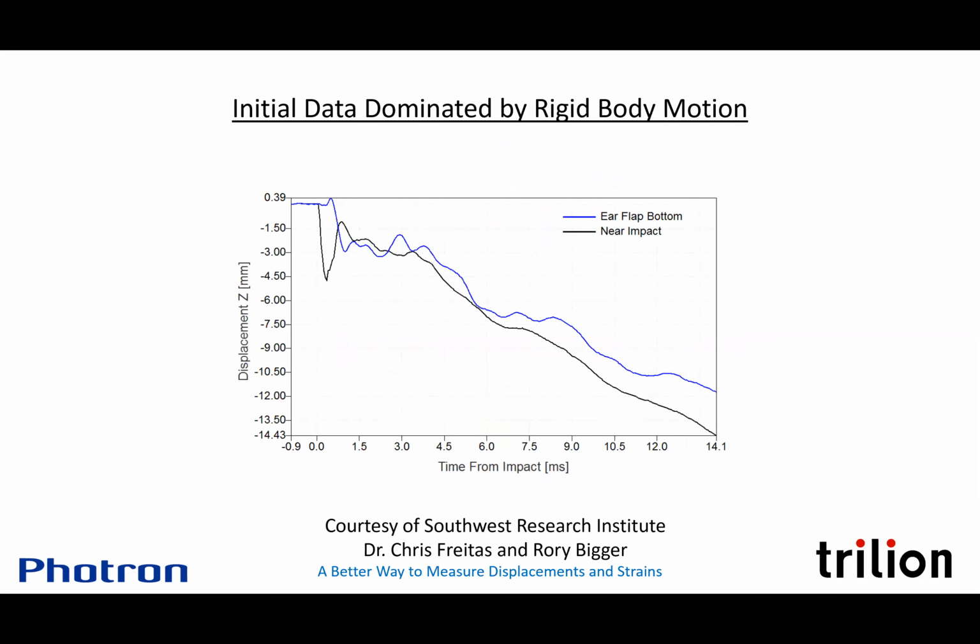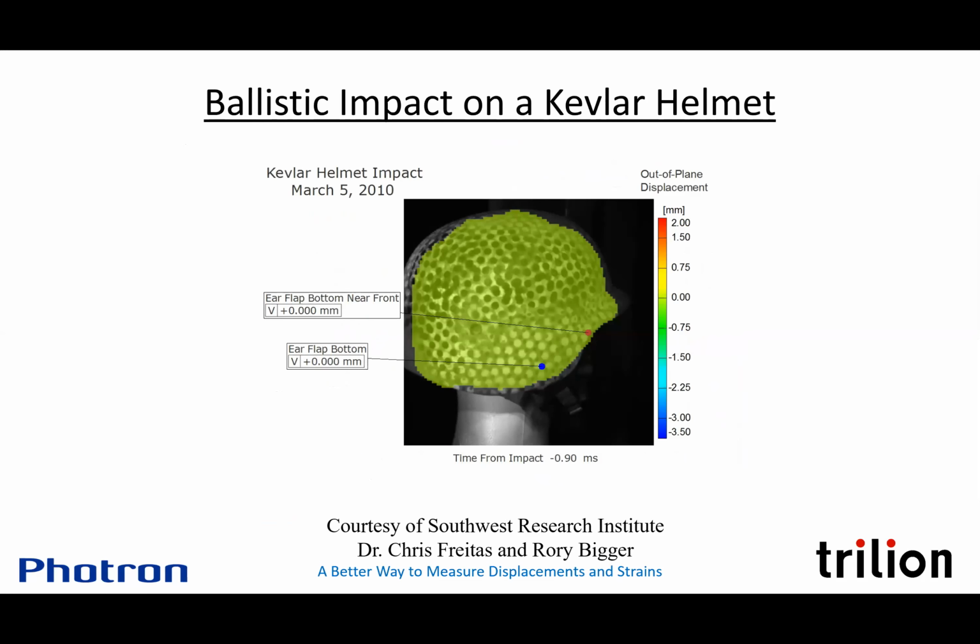Here we go. On this helmet test, if I can see my cursor, this area was having higher deformations. The points I used for the rigid body were up on this non-deforming section. When in doubt, using all points tends to work well. But if we know where there are deformations and where there's none or less, we can limit our selection of points. The other thing that's important is to pick points that are separated in 2 directions. So this way and this way.